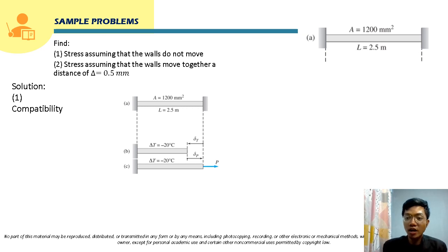Class, the next step is that we have to restore the restraint, or the force that causes the restriction. Since this is a fixed support, this deformation will be prevented because it is supported here. To indicate this restriction provided by this support, we will draw here the reaction force that will cause that restriction, and that is force P. This will maintain the length of this member.